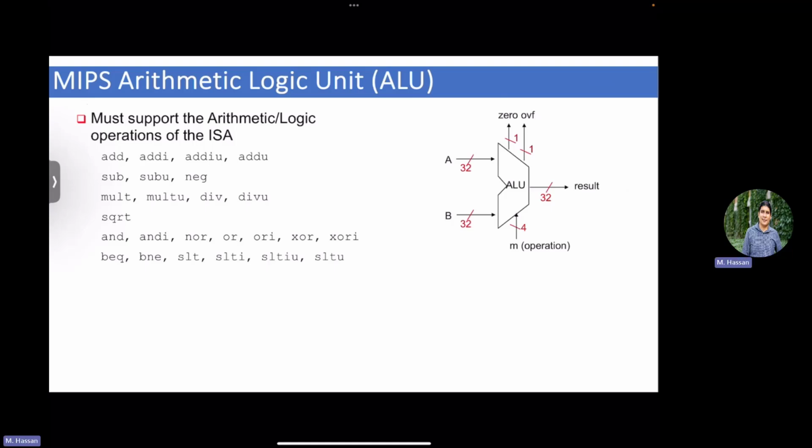A question to you from our previous lecture: who is going to drive these guys? Who is going to tell the ALU the value of these 4 bits to conduct the operation? The control unit, right? We said there is a control path. Its role is to fetch the instruction, understand it, and feed the bits to the execution unit with the right selection lines. Good.